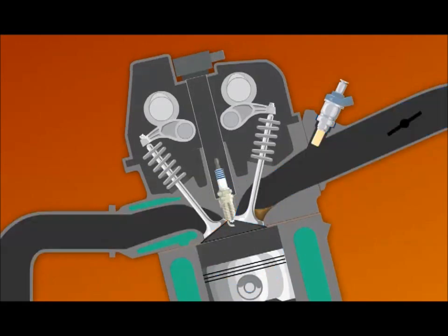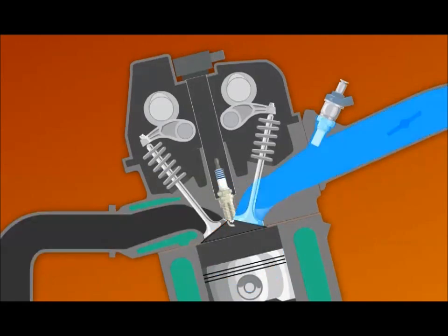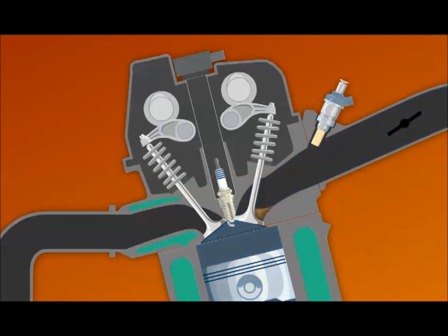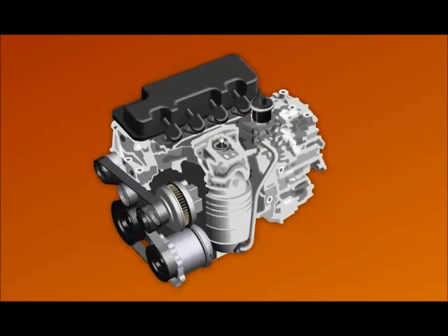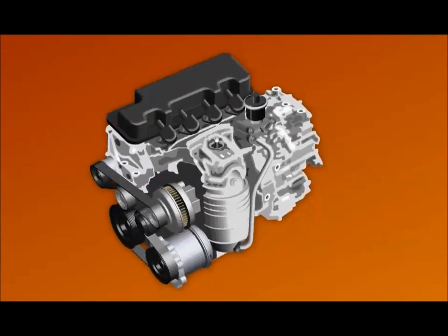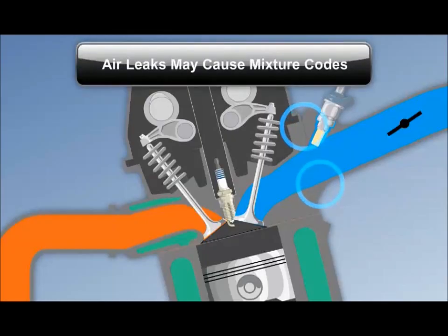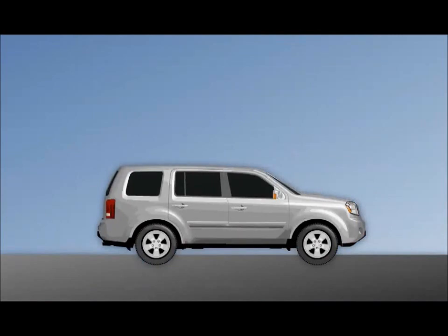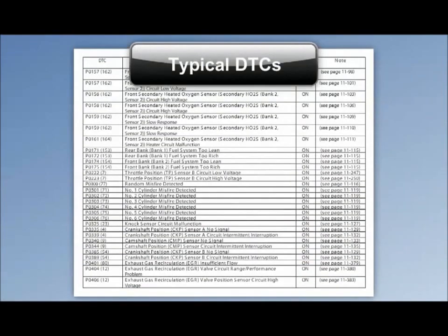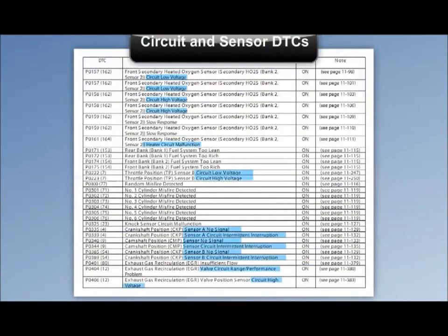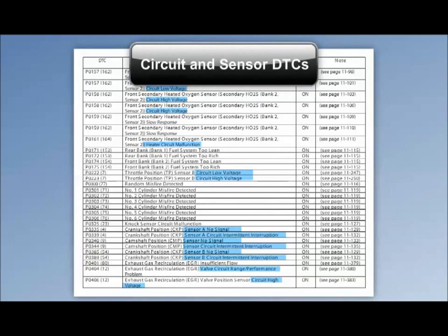Most engine faults affecting drivability involve problems in the intake manifold or combustion chamber. Faults such as intake manifold leaks, tight or leaking valves, or leaky piston rings can change the air-fuel ratio. These faults may lead to low power complaints or a rough idle. Because these complaints may set a DTC, a car with an engine mechanical problem may arrive at the shop with a malfunction indicator light.